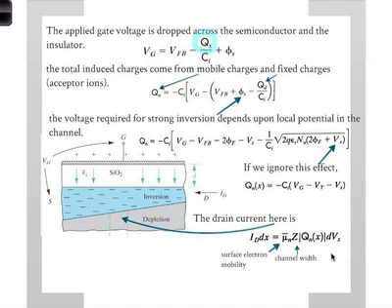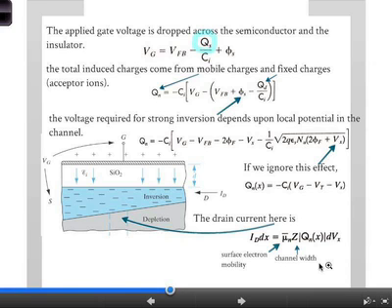Yes, because they're electrons, so you'll have negative charge. But it's not important for the current because you should know which way the current is flowing. But they will be consistent. So the current is essentially the local field times the mobility. We'll put this stuff in later. Times the number of charges.